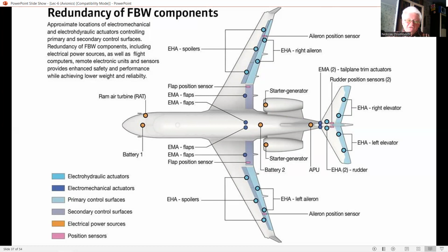Thus, if one system fails hard over, while another is demanding maximum control surface movement, the other 3 parallel good channels can override the failed channel. However, to survive a second failure, it is necessary to disconnect the first failed channel. Otherwise, it would be a stalemate, 2 good channels versus 2 failed hard over channels.